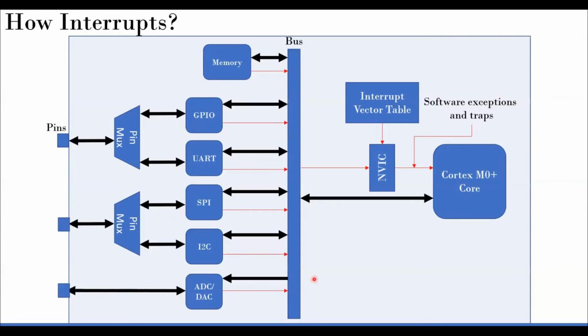So that bus is our friend all the time. Similarly, there's a memory unit, the SRAM unit, or even the flash memory unit, which is connected to the core through the bus. So inside the core, what is there? Inside the core, it's only registers and I/O, and maybe some other logic circuits. That's all.